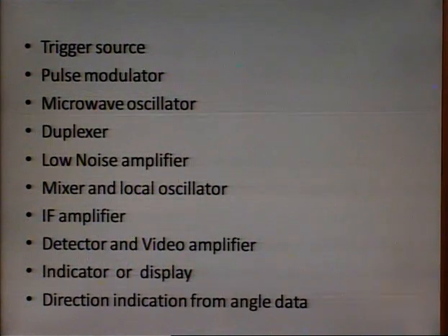The constituents of this are trigger source, pulse modulator, microwave oscillator, duplexer, low noise amplifier, mixer and local oscillator, IF amplifier, detector and video amplifier, indicator or display, and direction indication from angle data.